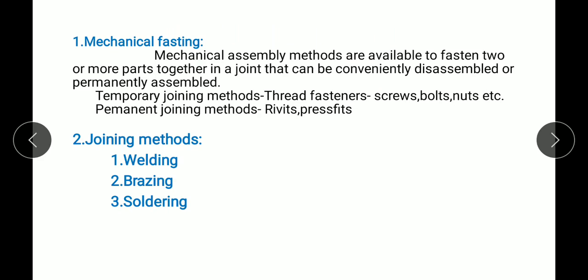Second one is press fit. Press fit means fits, which you already know. In the metrology subject we have clearance fit, interference fit, and transition fit. Here interference fit is nothing but press fit. Press fit means the hole diameter is very small when compared to the shaft diameter. So when some pressure is required to fit that object, that is called press fit.